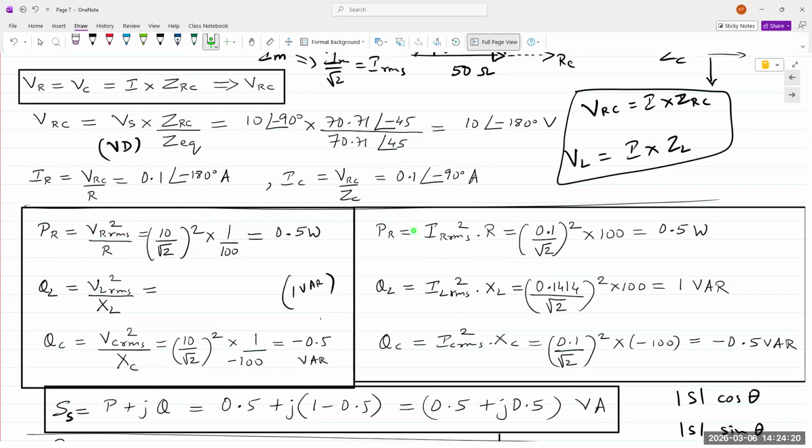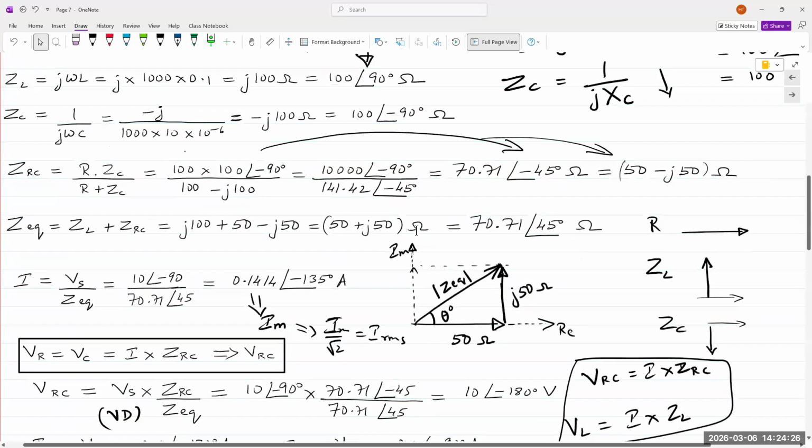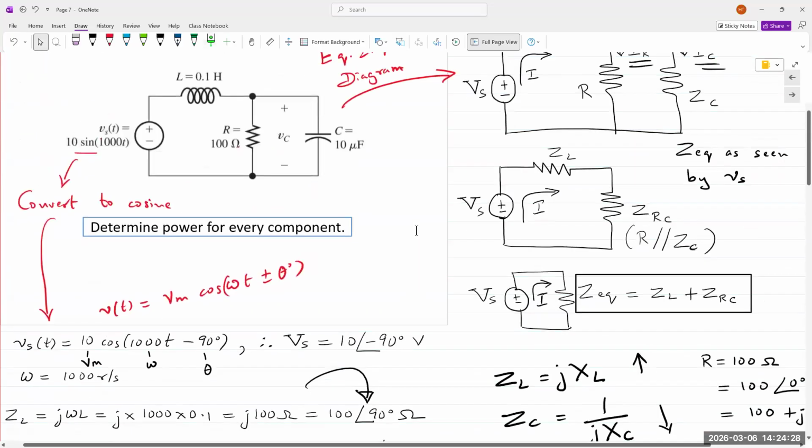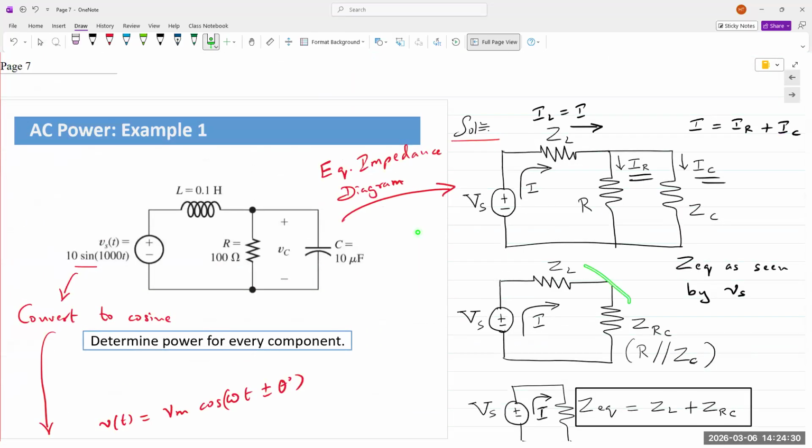If we wish to find the voltage, say in a 3 resistor circuit, we reduce everything down to one single resistance, apply Ohm's law, find the total current, and then expand it back up again. So that's what we're going to do here.